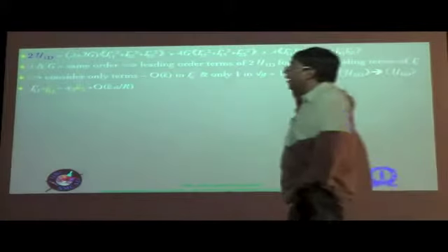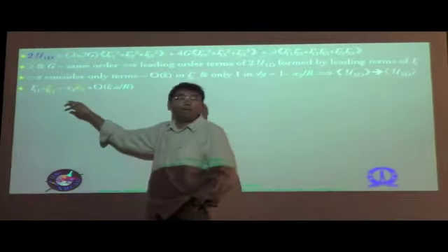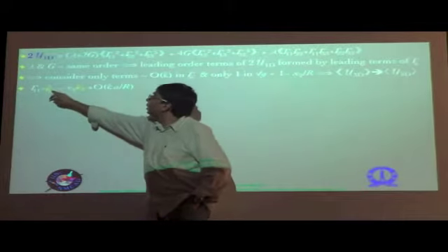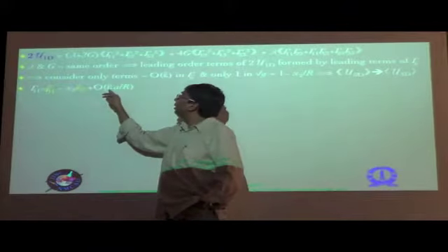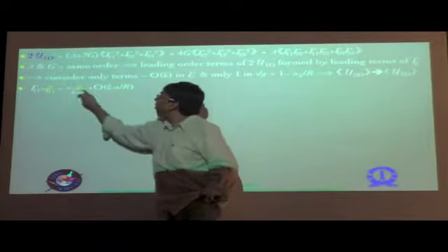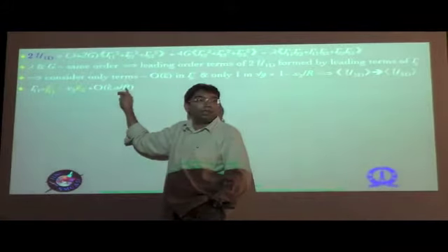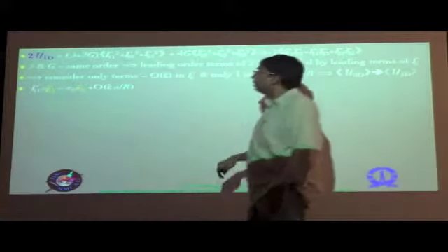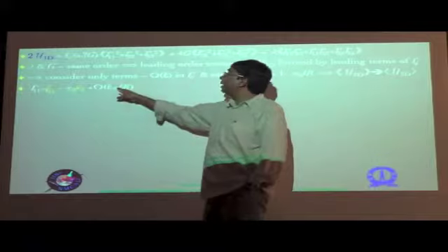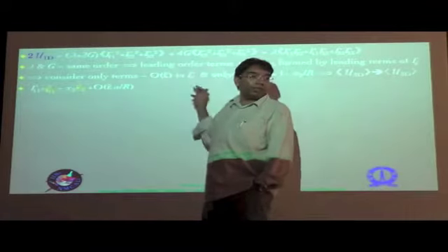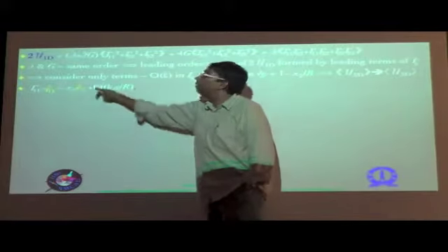So then we have gamma 1 1. Taking only the terms which were not underlined, we have only two terms, gamma 1 1 bar and x3 minus x2 kappa 3 bar. And then the next higher order terms are of the order of this, which is epsilon hat times a by r. This is not the terms which we wrote as HOT there. Those were epsilon hat times a squared by r squared, the next higher order terms. We are dropping even those terms which we underlined. Those terms which we underlined were of this order, right?